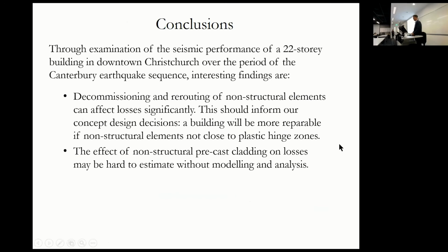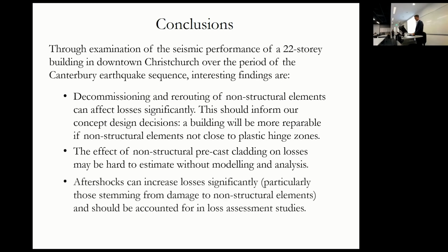The effect of non-structural precast cladding on losses may be hard to estimate without modelling and analysis. And maybe you could make that a bit more general and say, well, it could be certain types of non-structural elements. It's a bit hard to anticipate. We have to step back and think carefully before we decide on their impact. And aftershocks can increase losses significantly and should be accounted for in loss assessment studies.